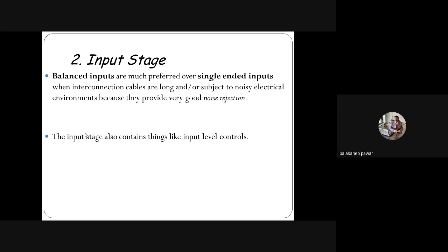That is nothing but dual input balance output differential amplifier that you might have studied in your integrated circuits, right? Dual input and balance output means what? In that differential amplifier, there are two inputs and the output is taken out from the collector of both transistors. If you can recall that circuit diagram, that is dual input balance output differential amplifier, then you will get clear about this, right? So the feature of that dual input balance output differential amplifier is its good noise rejection ratio,